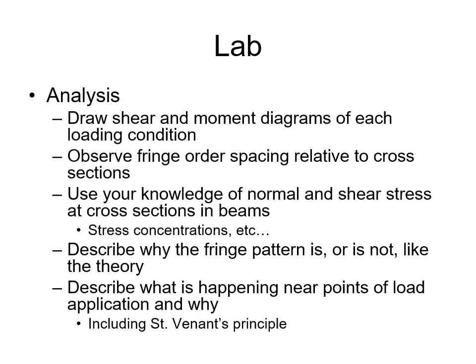So for the analysis portion of this lab, we're going to need to draw shear and moment diagrams of each loading condition. We're going to observe fringe order spacing relative to cross section. You use your knowledge of normal and shear stress at cross sections in the beams, stress concentrations, etc. You can describe why the fringe pattern is or is not like the theory, and describe what is happening near points of load application, and why.